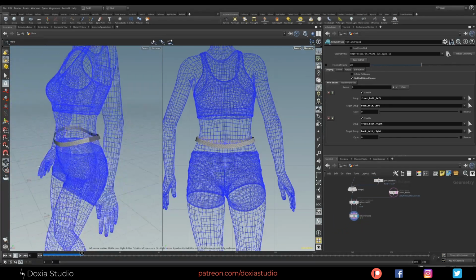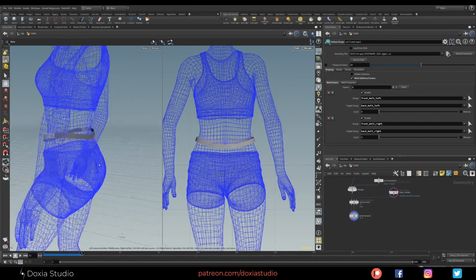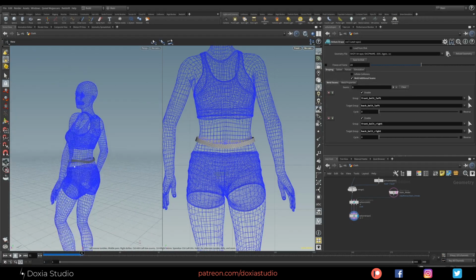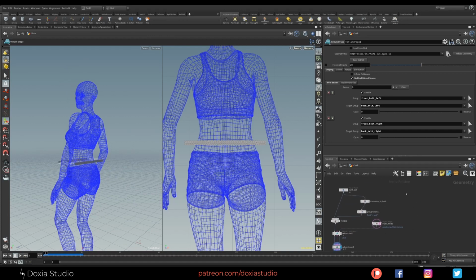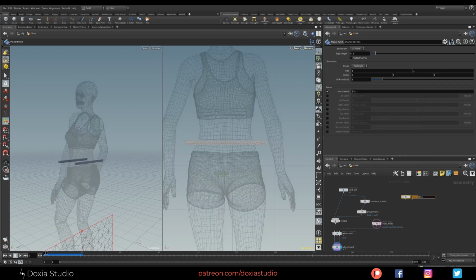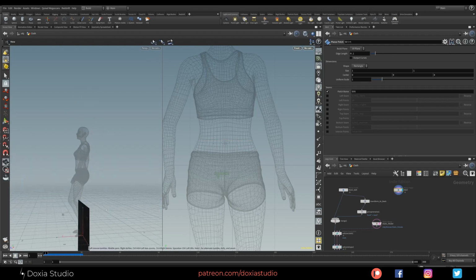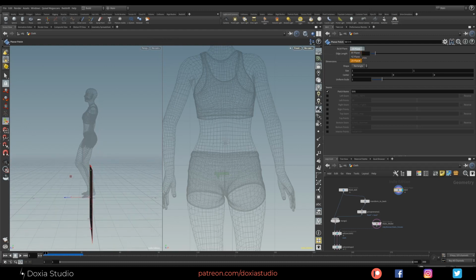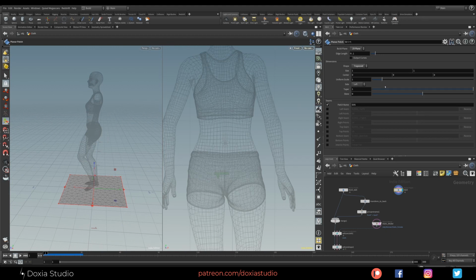Okay, now let's make a skirt, to stitch to the back of our belt. To make the skirt, let's place another planar patch, call it skirt. Okay, let's make a skirt. We want the skirt to be on the Z and X plane, and I want it to be a trapezoid. A trapezoid is a little different from the rectangle because you can scale one of the sides.